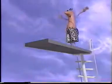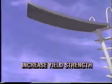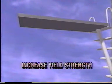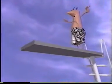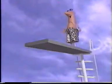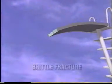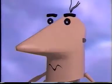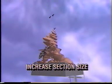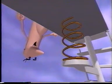To prevent yielding in service, however, it might seem logical to increase the yield strength of the part by heat treatment or using some other metal. Well, sometimes this can be done, but if a metal already has a high yield strength, increasing the strength even more may lead to a more serious type of failure, brittle fracture. Yield strength might also be increased by increasing the section size. We beef it up to reduce the stress. Well, this can be done in some cases, but this can also affect the function.